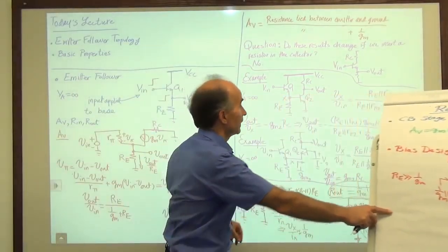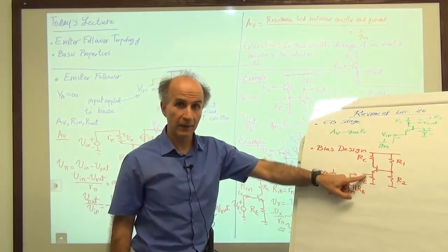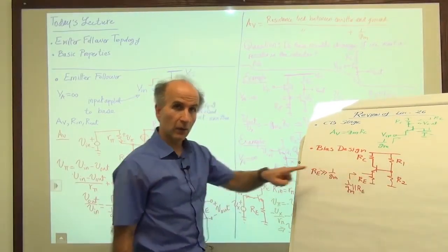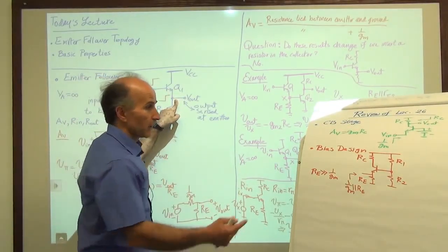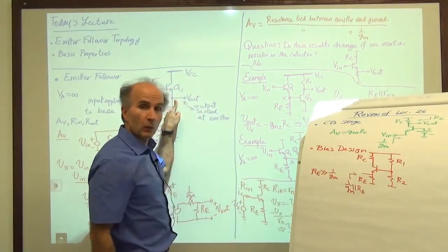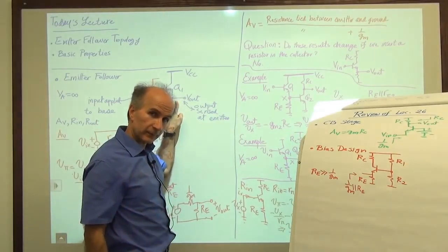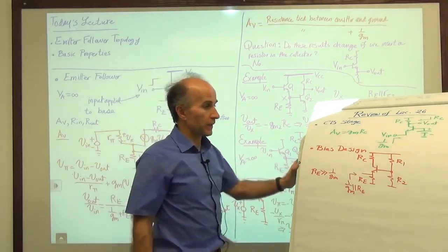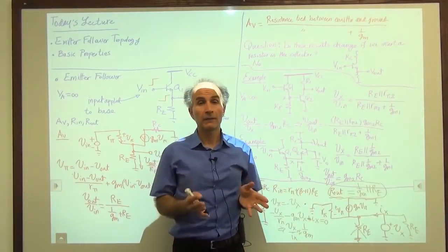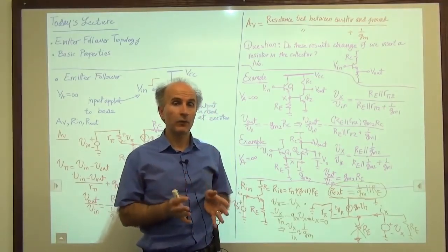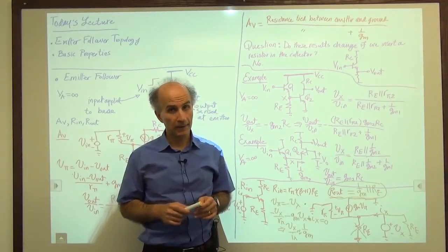So whether we have this circuit as a common base stage and we are sitting here and looking into the emitter, or whether we have this circuit and looking into the emitter, we should see the same thing, because this resistor doesn't play a role in what the circuit does, as long as early effect is neglected. So that's also interesting. That points to yet another important fact. If we are interested in the output resistance of a circuit, we don't know where the input is.